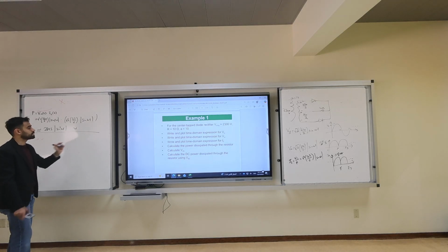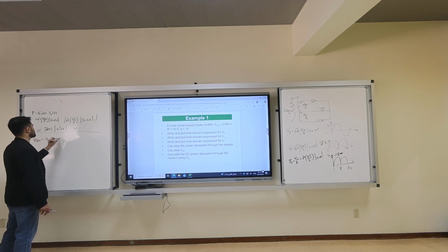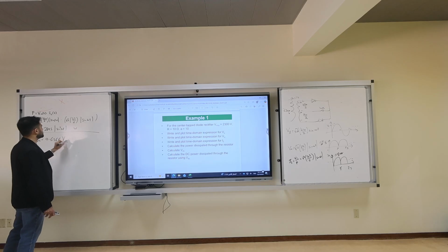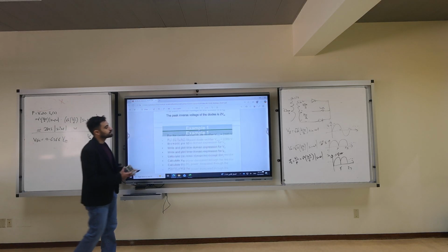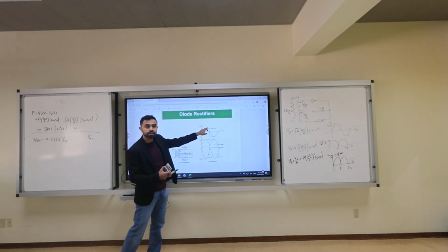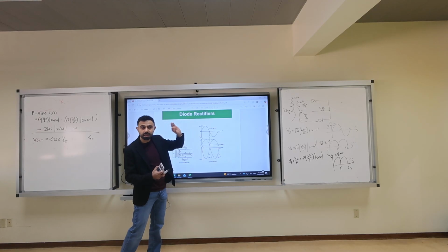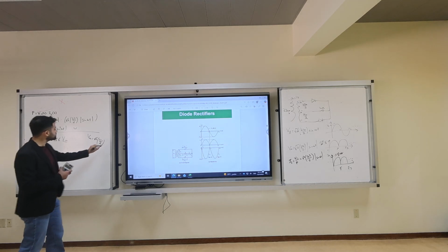Okay? Try it. What is VDC? VDC is 0.6366 Vm. But what is Vm? Vm is, you go to the drawing, the peak of Vs. So what is the peak? It is square root of 2 times 230 over 2 volts.